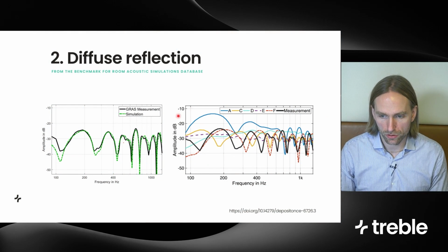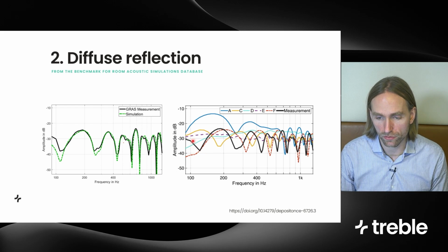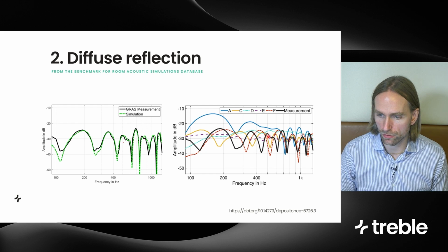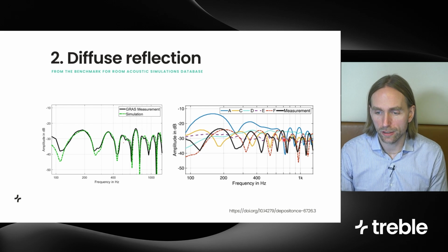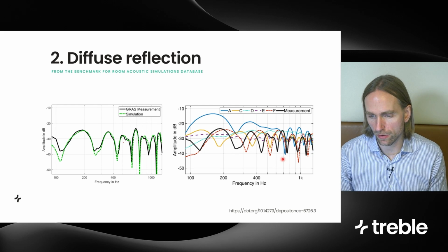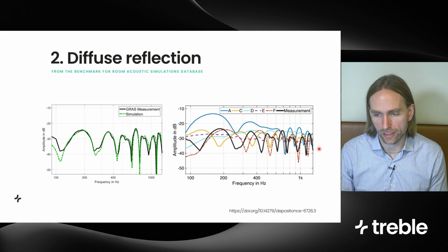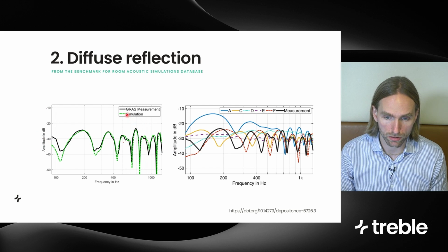If we first turn our attention here to the right, this is from the paper of the authors of this database. And then we see the measured frequency response here in black between the source and the receiver. And then these are different simulation tools available in 2019, I believe, all geometrical acoustics based, trying to model this scenario. Because they don't model diffraction and interference and things like that and complex geometries very well, they are not able to model this kind of scenario, complex geometries and complex acoustics. However, if you do a wave-based simulation here in the low mid-frequency range, then with Treble simulation, you will match this very well.